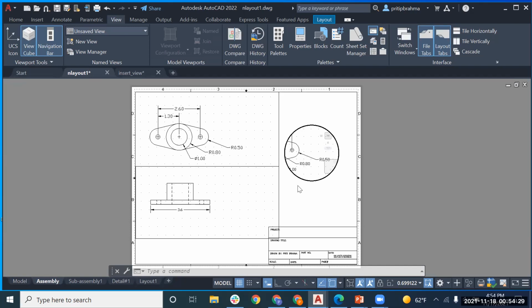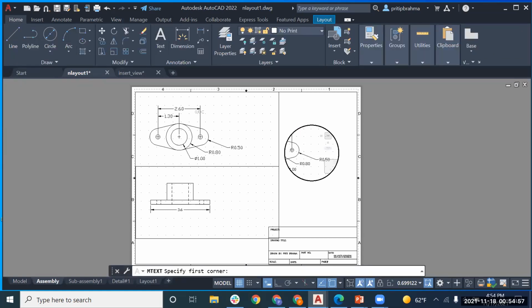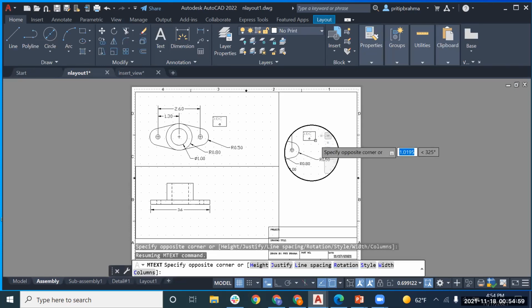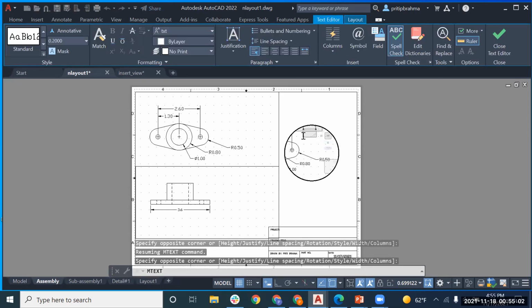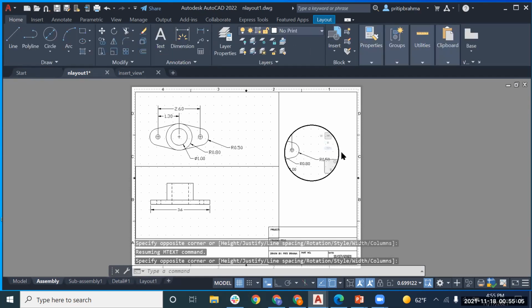Okay, and do those callouts show the magnification factor, or is that just something you can easily see? They don't. You're right, I was hoping someone would ask that. Everything down here on scale is going to be relative to these normal orthographic views. Something like this, you would put a note in that says enlarged 10 times or something like that. You could put a text in. You can go to Home and add text in any window right here. So you could add text right there that says what your enlargement scale is on that. Thank you. You're welcome.